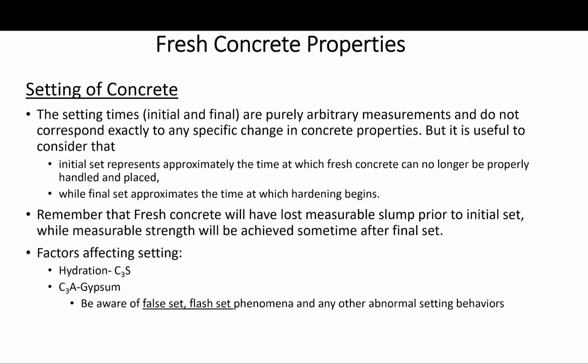So what really affects the setting? It is obvious the hydration of the cement phases will affect setting. Definitely the C3S. It should be remembered that cement hydration begins as soon as water is added to the mix.